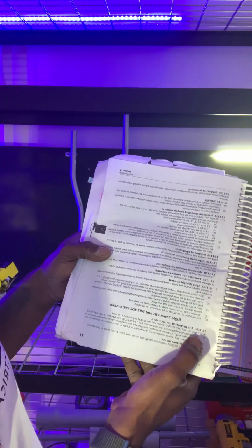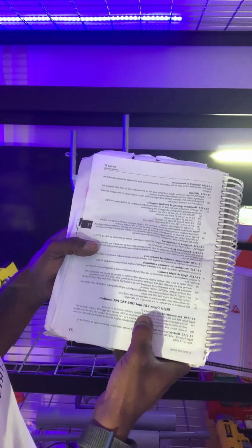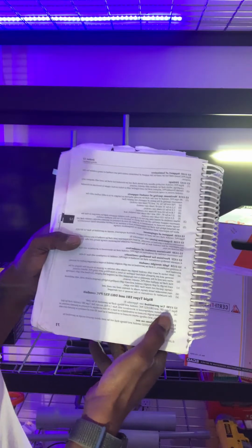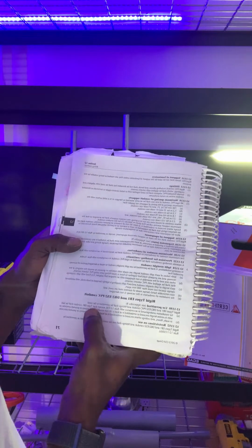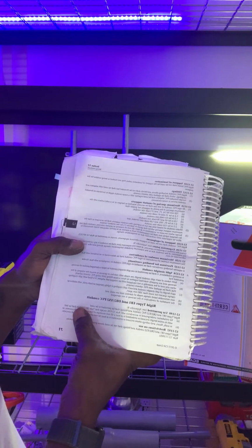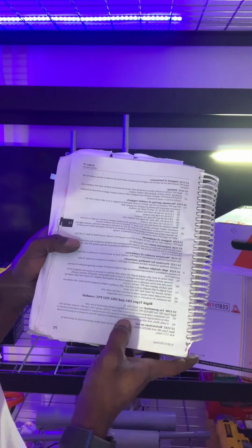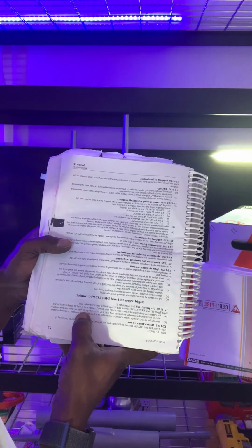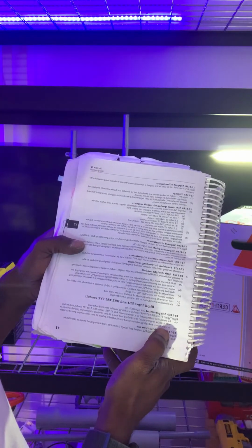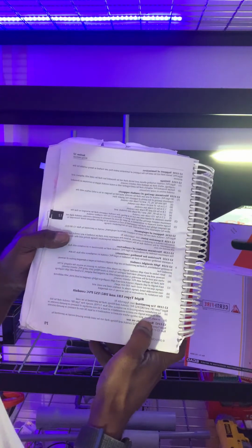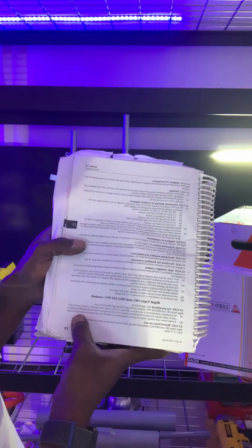See Appendix B. Rigid types EB1 and DB2/ES2 PVC conduit and fittings shall be permitted to be used A, for installation underground in accordance with Rule 12-930, except that type EB1 conduit shall be laid with its entire length encased or embedded in at least a 50mm envelope of masonry or poured concrete, or B, in walls, floors, and ceilings where encased or embedded in at least 50mm of masonry or poured concrete.